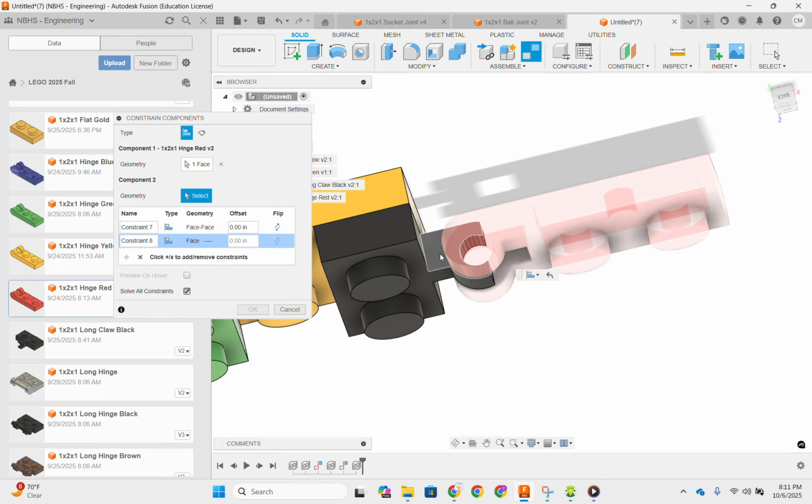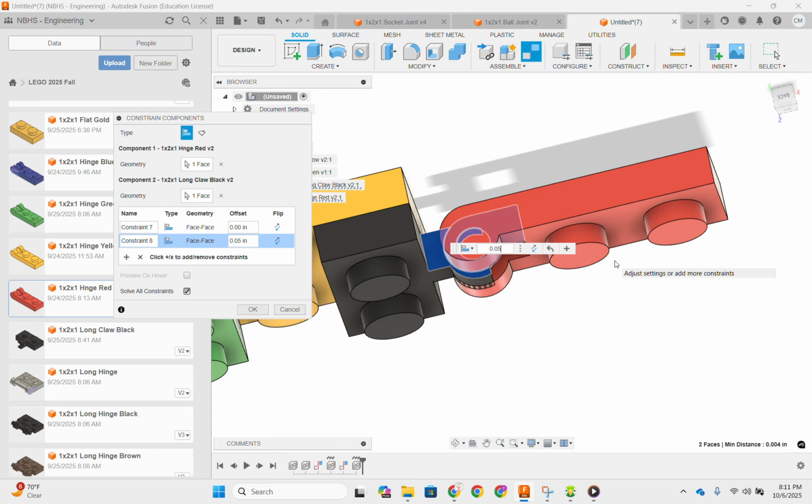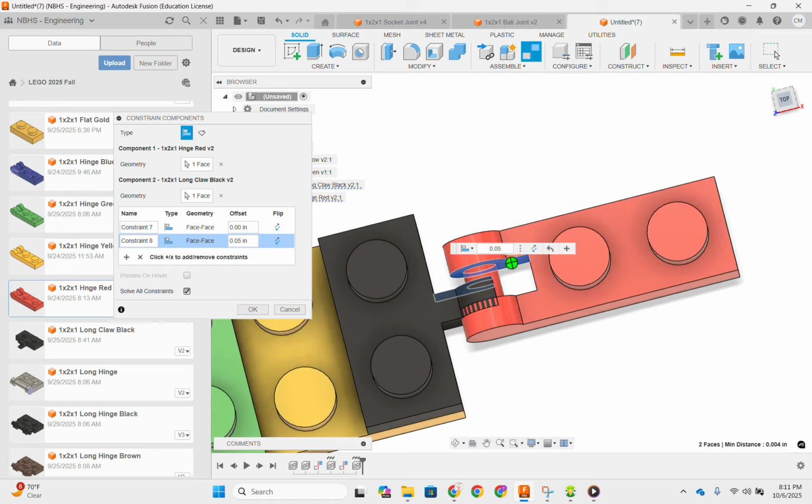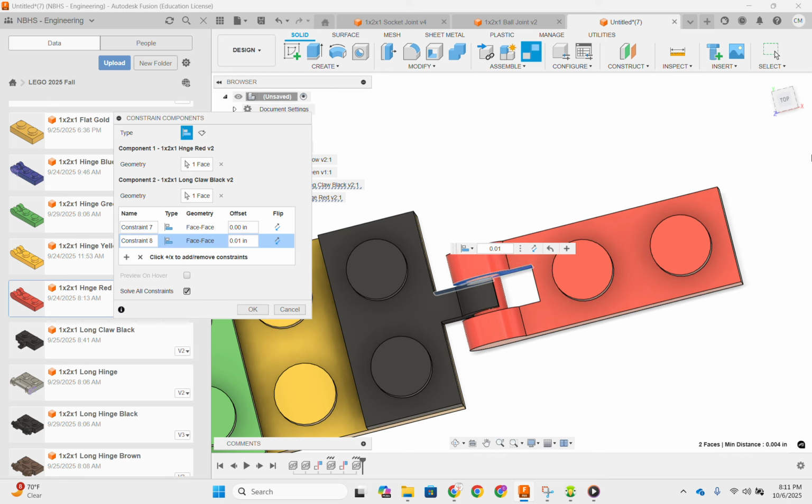and this face right here, and I'm going to give it, I'm sorry, mine's set to inches. I'm going to give it something like 0.05 inches, something like that, just a little tiny bit of a space. Let's see, that's way too much. So let's try 0.1. That's a little closer. Alright, you should be in millimeters. Mine's still set to inches from another project.